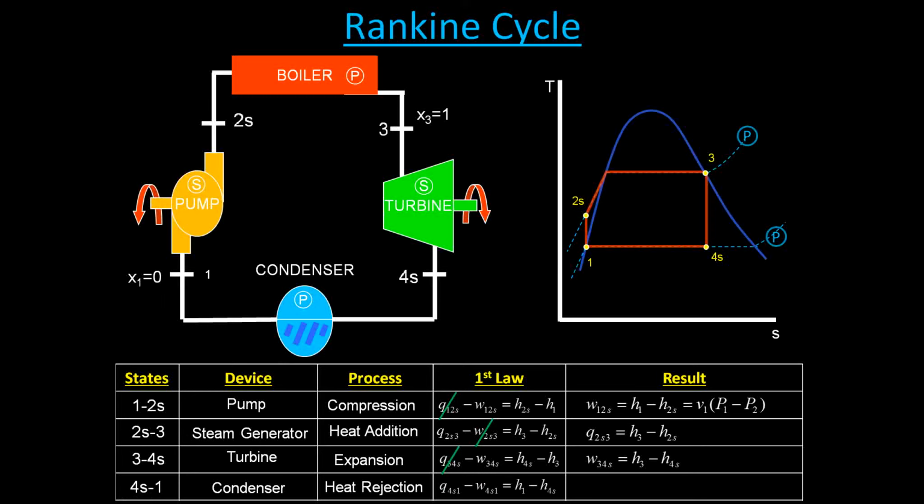So we look at the conservation of energy. Again, in this case, it's a heat transfer device, so there's no work involved, so the work term goes away. We rewrite as the heat transfer 4s to 1 is equal to enthalpy 1 minus enthalpy 4s. Now for these equations, for the pump process, we should, according to heat in, work out,